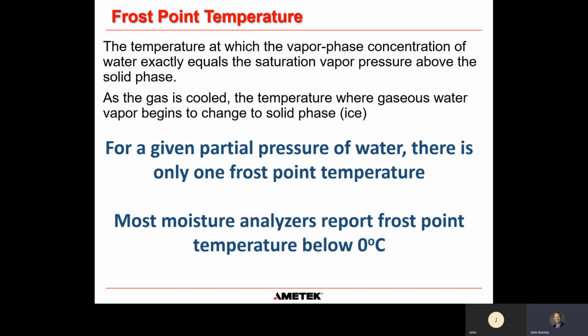The other term you might hear is frost point temperature. The only difference between this and dew point temperature is that as the gas is cooled, this is the temperature where the first molecule of water vapor begins to come out, instead of as a liquid, as a solid, and it's ice. So that's frost point temperature. And just like dew point, for any given partial pressure or vapor pressure of water, there's only one frost point temperature. One thing to note is most moisture analyzers in the industry report frost point temperature under 0 degrees C and dew point temperature above 0 degrees C.